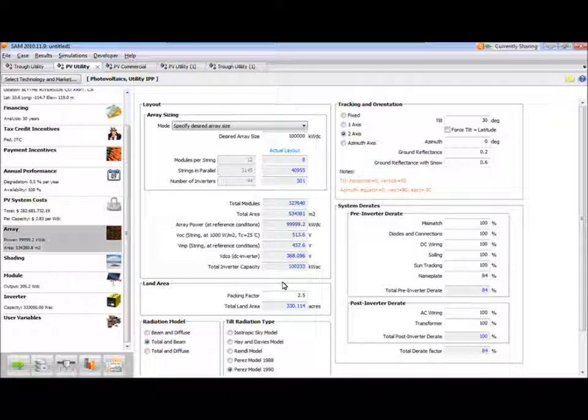You can size the PV array and inverter bank as you wish, if you're trying to optimize cost or production. So basically, when the array is outputting more than the inverter, it will just cut off the excess. Okay, thank you.